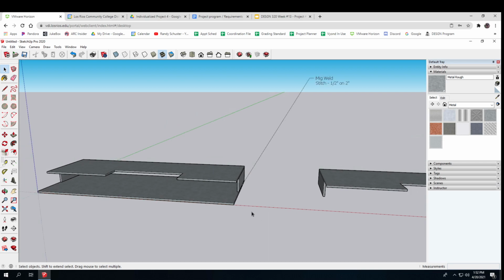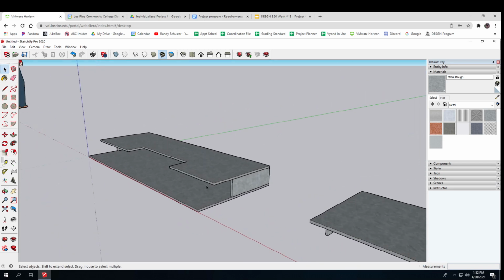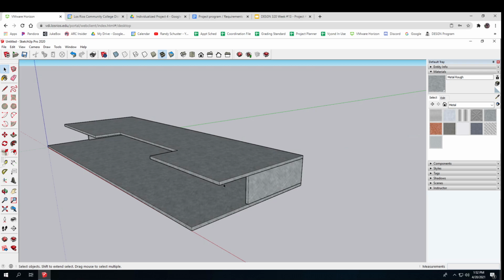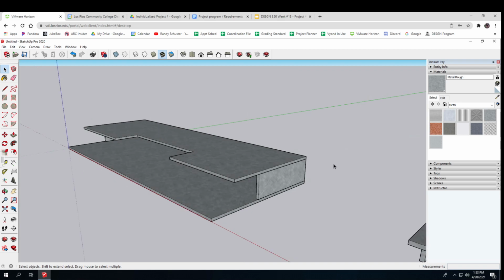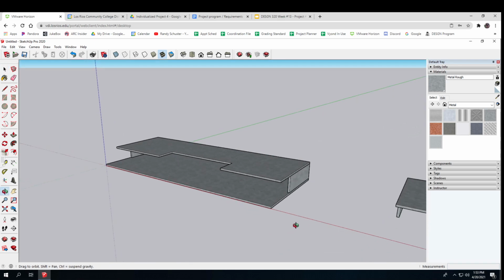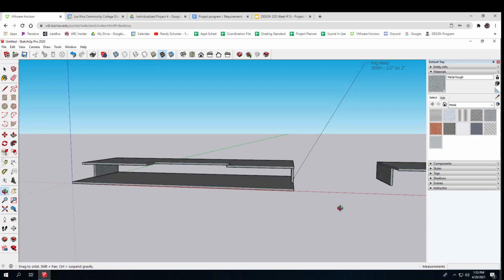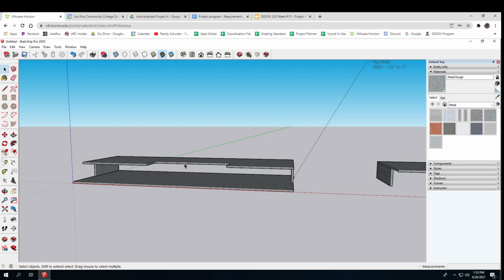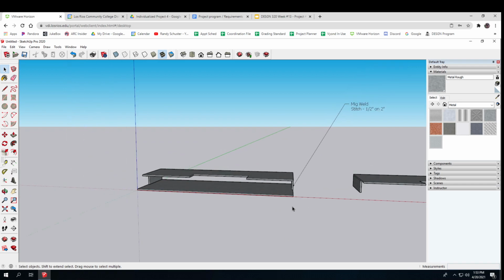And then, if I was making this out of metal, I would probably put just a little bit of a bend somewhere underneath to stiffen this somehow. Because if this is metal, it's going to be really saggy, baggy. But if it's 1/8 inch metal and I put a bent lip on it, it gets really strong. So it depends on how much you know and how much you've done this kind of stuff as to what kind of design you would end up with. But that's how I would get going with it. Any questions on that?